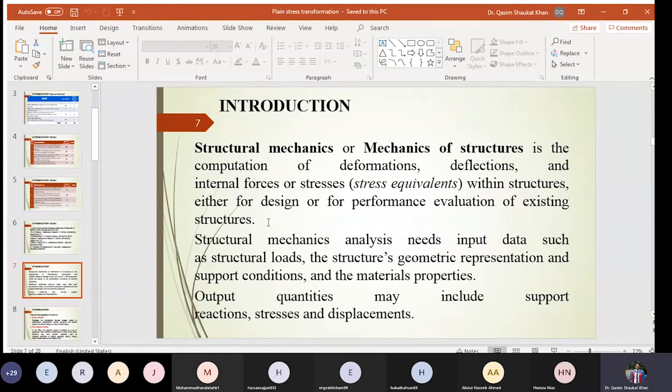You might have seen structures general design life is, let's say, 25 years, but even after 25 years, your structure is performing reasonably. So you want to see how much is the strength, capacity of the existing structure. So for the existing structure, what we do, we take the cores out of the slab, beams, columns, walls, just like the cylinders.